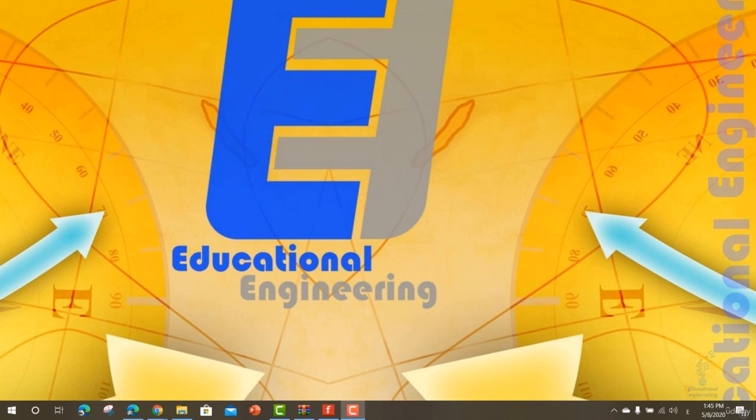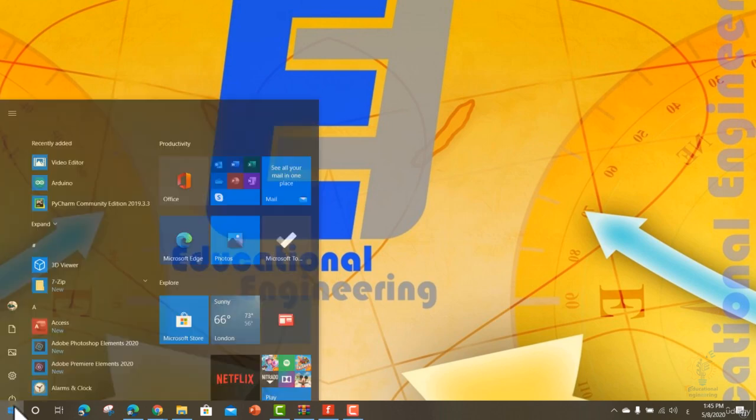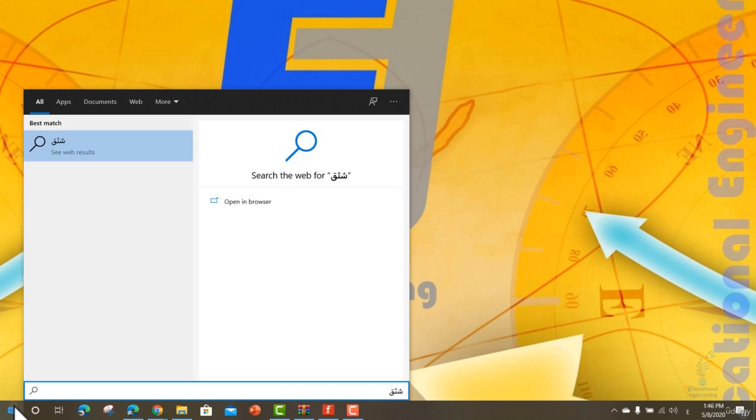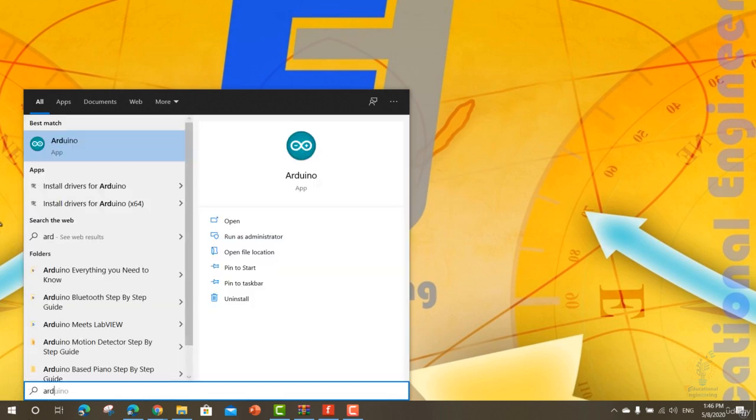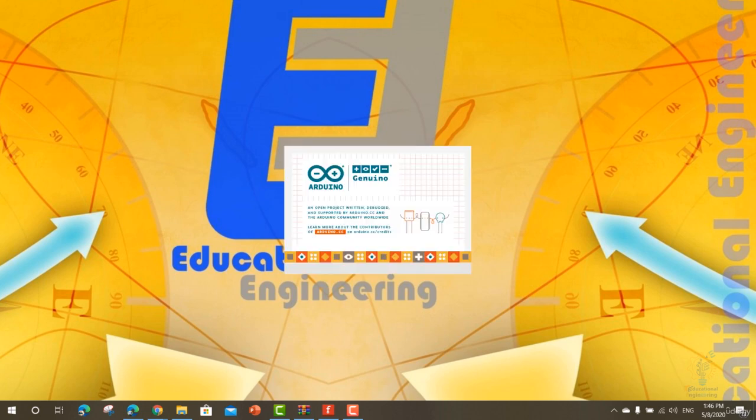We are going to demonstrate how to turn the ESP32 into an access point and serve up web pages to any connected client. To start with this, first you need to plug in your ESP32 board and run the Arduino software. We already explained how to download and install the software, and how to get it to recognize your ESP board.